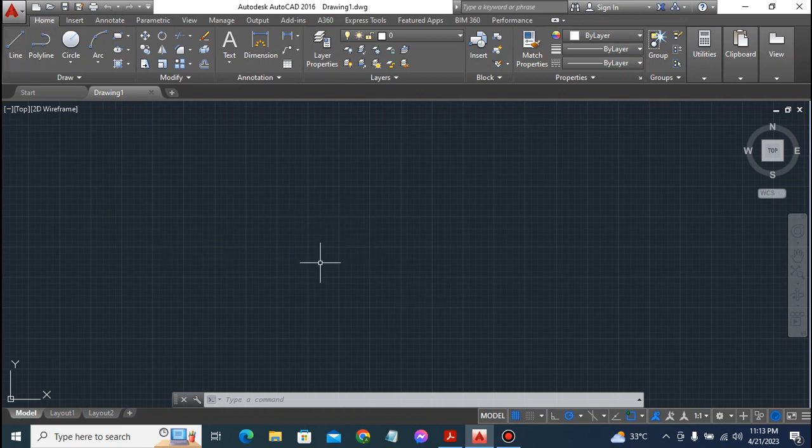For the beginners, this is your first approach towards drawing a line in the AutoCAD environment. So we've taken cognizance of the coordinates of point A. In order to draw this line, we have to select the line tool. We have to tell AutoCAD we want to draw a line. You click on the line tool, which is here at the top left of the screen. You see where my cursor is right now. You click on line. Once you've done that, there is a tooltip highlighted, telling you to input the coordinates of the point you want to draw.